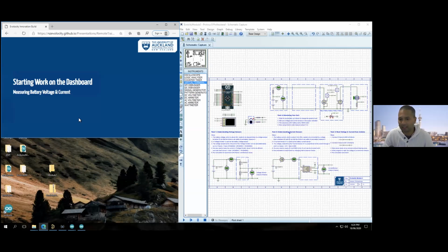From the battery voltage, we can figure out whether the battery is fully charged, how much it is discharged down to, how it is performing, all these sorts of things. From the current and the voltage, we can work out the power that's going into the motor. So these are two critical things in your design: knowing how much power you're putting in, knowing how much current goes into the motor, and knowing the status of the battery.